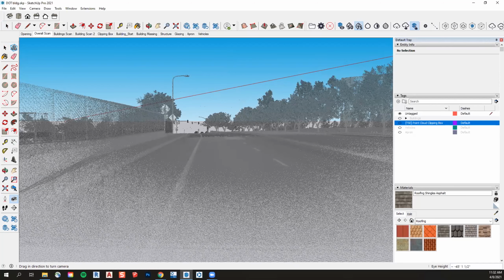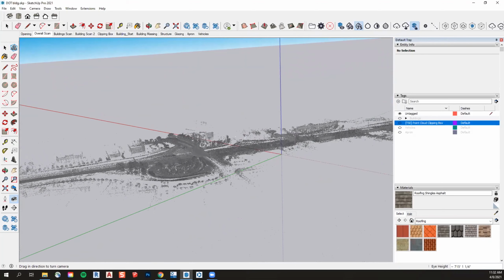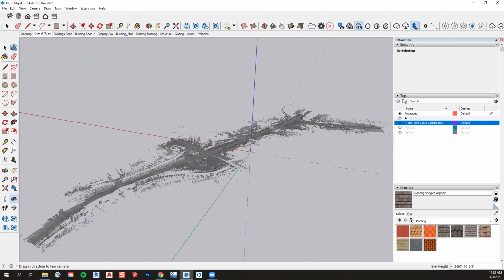So for this exercise, we're going to say that we've got a building in this example that works really well for us. We want to replicate that building further down the highway, but we don't really know the best place for it yet. So we've got a scan. We're going to focus on this building and use this. You'd use the same workflow for a bridge, river locks, hangar renovations, really anything that you can model in SketchUp. We can use Scan Essentials to make sure that we're accurately modeling the existing conditions.